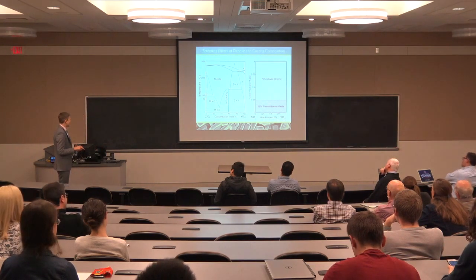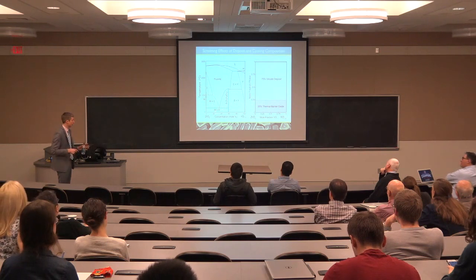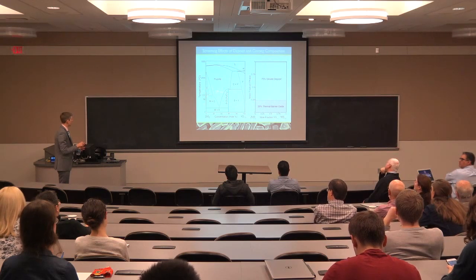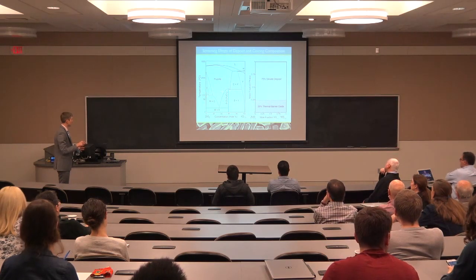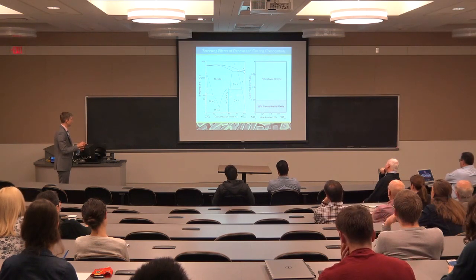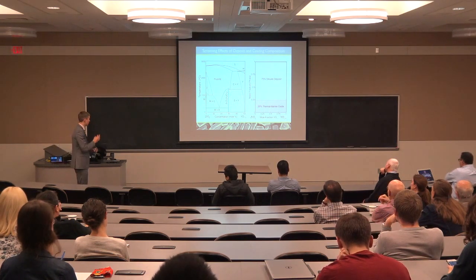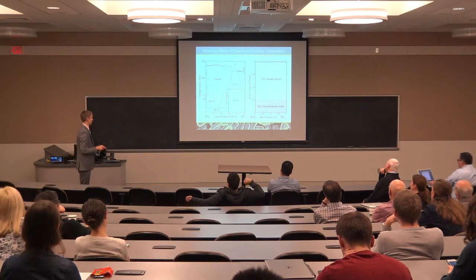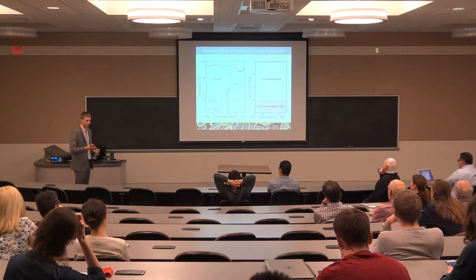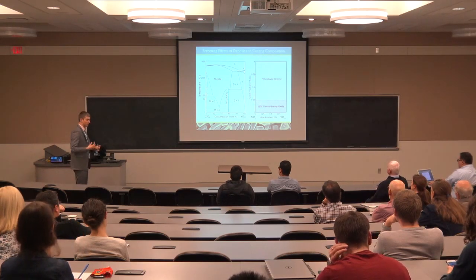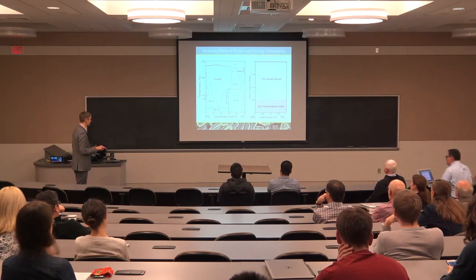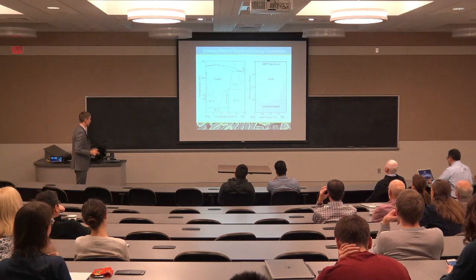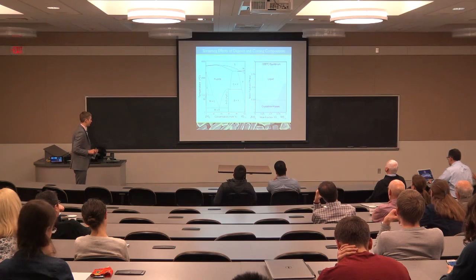In these materials, we have a pretty wide design space, in the sense that the traditional thermal barrier coatings are over in this area. We've got a large solid solution field here, this fluorite phase, we've got this line compound, and we've got this two-phase field that might also be amenable to making coatings. And so our question is, if we pick a certain threshold of coating dissolution, maybe we say a certain amount of the coating dissolves into the melt, how does the fraction of phases that crystallize as a result of that reaction change as we change the amount of the rare earth element in the coating? So we might say, if this is our starting point, how much crystalline phase do we get as a result of those reactions?